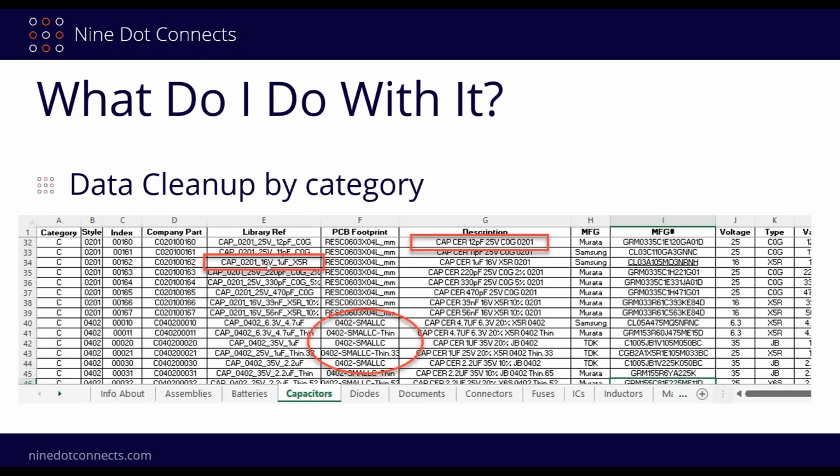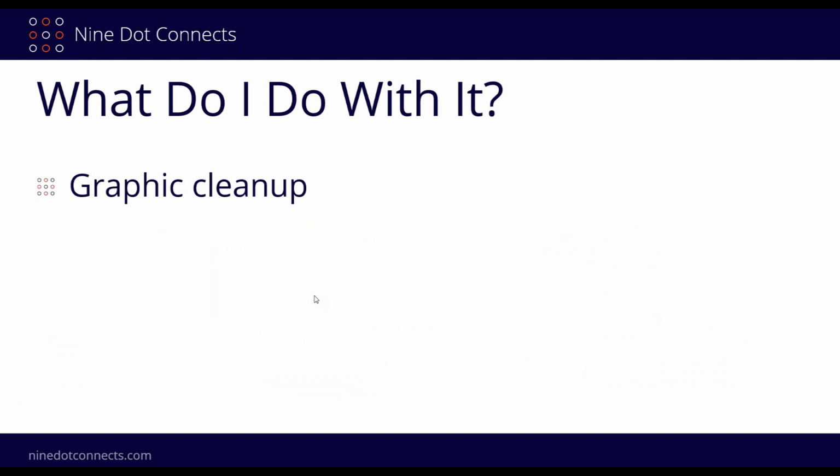And then even their library references, I thought they did a really solid job with this as well. So I basically squared it off, not circled it, but squared it off just to give that example. I was also humored by the fact that their footprints were not necessarily following standard, but really the key thing is the description, because this is what's going to end up in the bill of materials, or just having a constant format. Even the voltage here is constant. There's no V's in here, no volts in here. It's very, very consistent, which is a good thing.